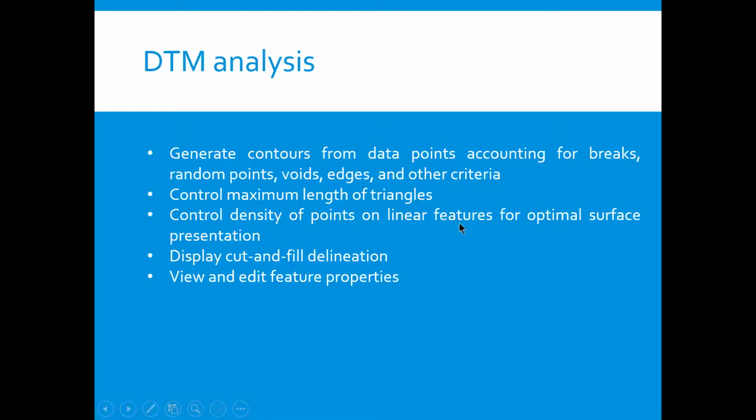DTM analysis, which stands for Digital Terrain Model, will create contours from data points accounting for breaks, random points, voids, edges, and other criteria. Control maximum length of triangles. Control density of points on linear features for optimal surface presentation, and display cut and fill delineation, view and edit feature properties.